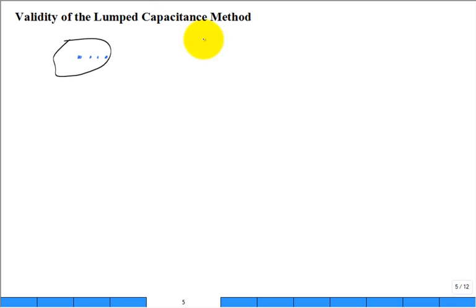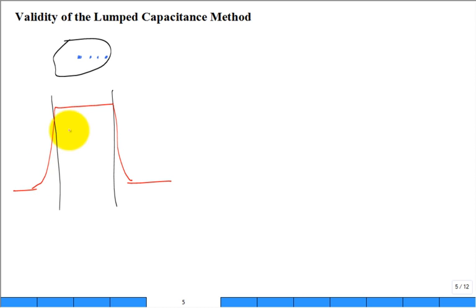What you do is you think of maybe a temperature in a slab that's convectively cooled. Let's say the temperature starts uniform, very hot. We subject it to a cool fluid. The fluid is way down here in temperature, and you get a dramatic temperature drop like that. And over time, the temperature has a little bow in it, just a little bit, but the majority of the temperature difference between the object temperature and the fluid temperature is just in the boundary layer, in the convection resistance. And so it continues to cool like that.